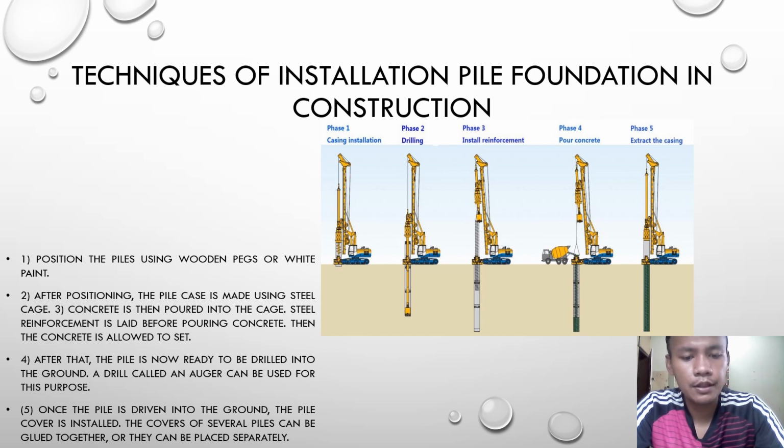Piles should be hammered into the ground until the refusal point is reached, which is the point where a pile cannot be driven into the soil any further. The method of installation of piles is a major consideration in the structural integrity of pile foundation.